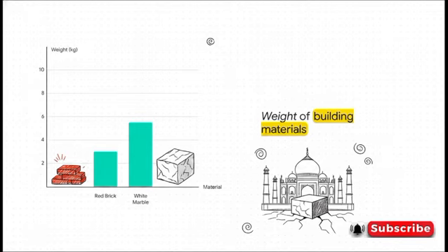That brilliant white marble, it's just a casing. It's like a veneer applied over the bricks to deceive the eye. And there's a brilliant engineering reason for doing it this way. You see, a standard red brick weighs about 3 kilograms, but a similarly sized block of solid marble weighs 5.5 kilograms. That is 83% heavier. If the Mughal engineers had actually built the entire structure out of solid marble, the sheer crushing weight would have completely obliterated that delicate riverbed foundation.